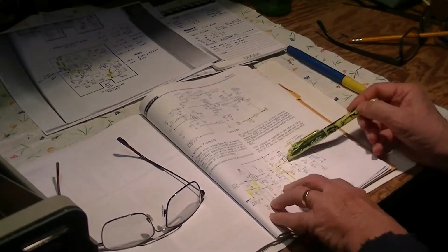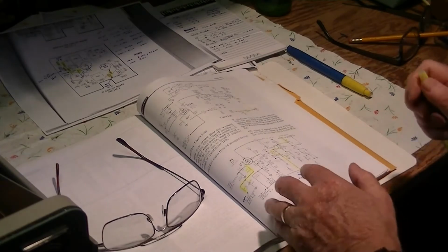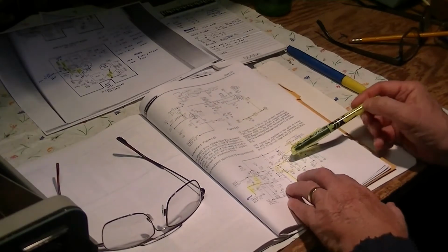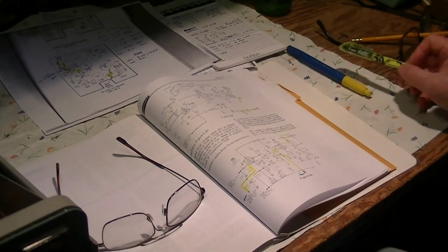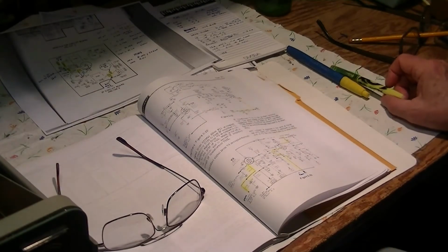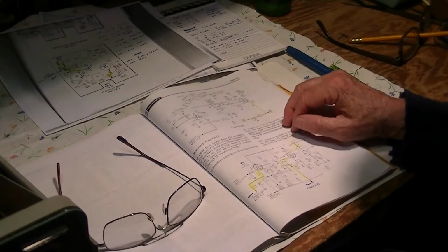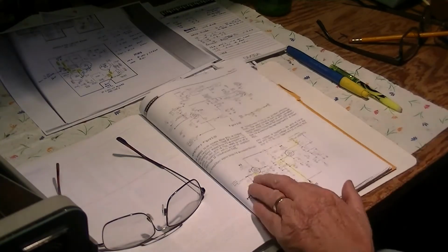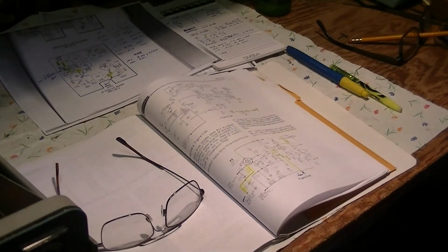The negative voltage on the grids of these tubes sets the point of operation for the tube and the amplification factor. So it's very important that all of these resistors in the grid circuit, they're all part of the bias circuit for the grid of the tube, and it's very important that those things not be very far off of their designated value. 10% is okay, 20% not. So nowadays we've got good 1% to 5% resistors, and so what's the point of having something that's wildly off? Now there's something else to be considered.